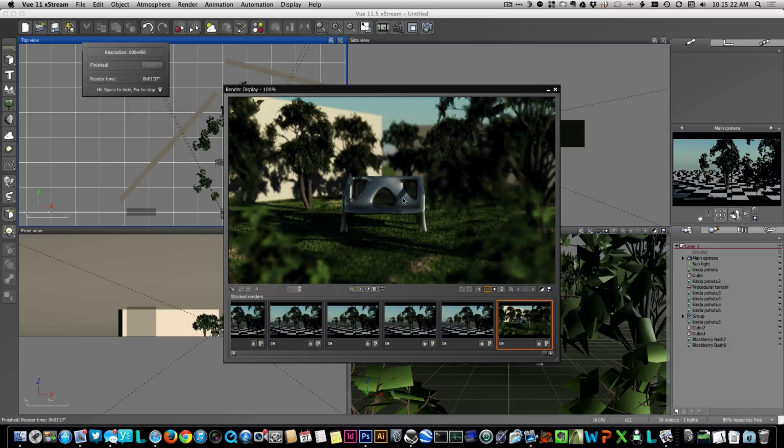blur. But another thing actually as well, it's not going to blur reflections. Fortunately, I don't think I can really see the reflections. If I was looking at a mirror, for example, the depth to the mirror is going to dictate the blur, when in actual fact, if you trace the rays, the blur in the mirror is to the object, not the mirror. So that depth effect wouldn't work with shiny objects. The fast or the hybrid, or the Photoshop blurring isn't going to work for mirrors and reflective materials as effectively as the ray trace one.